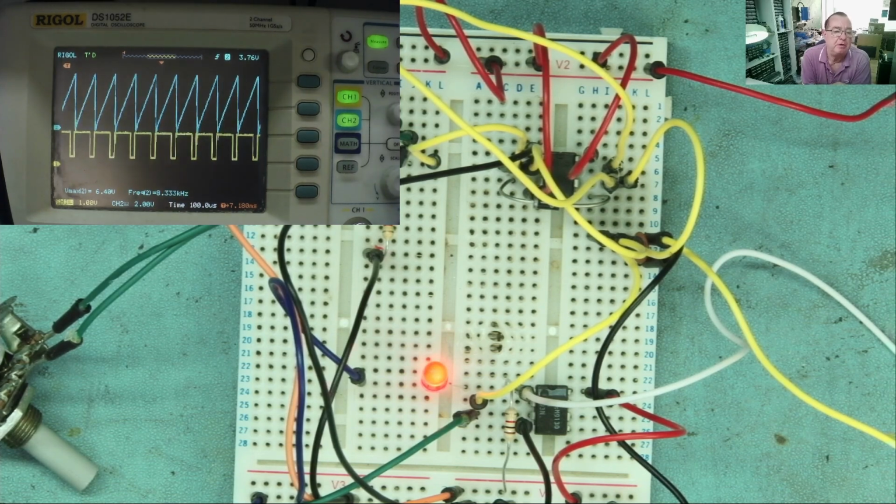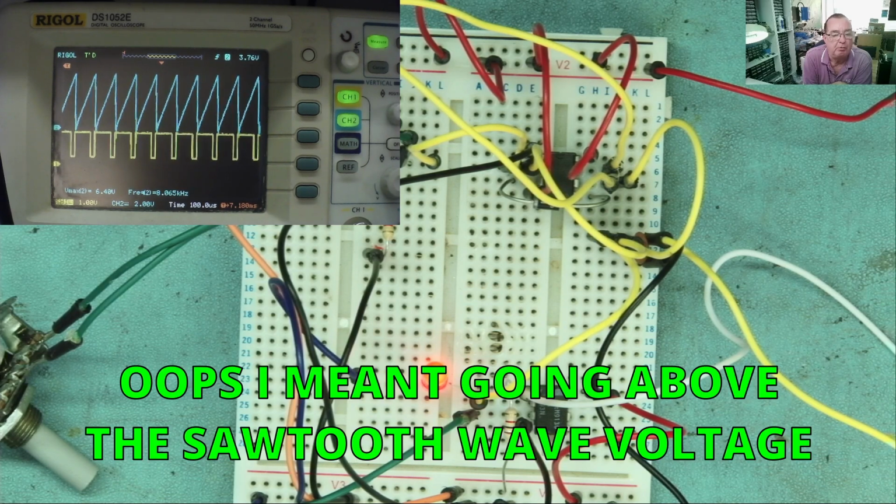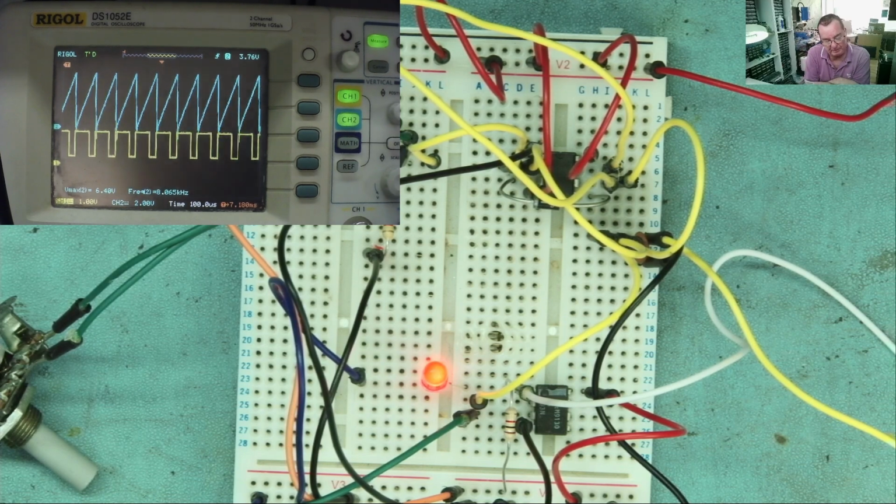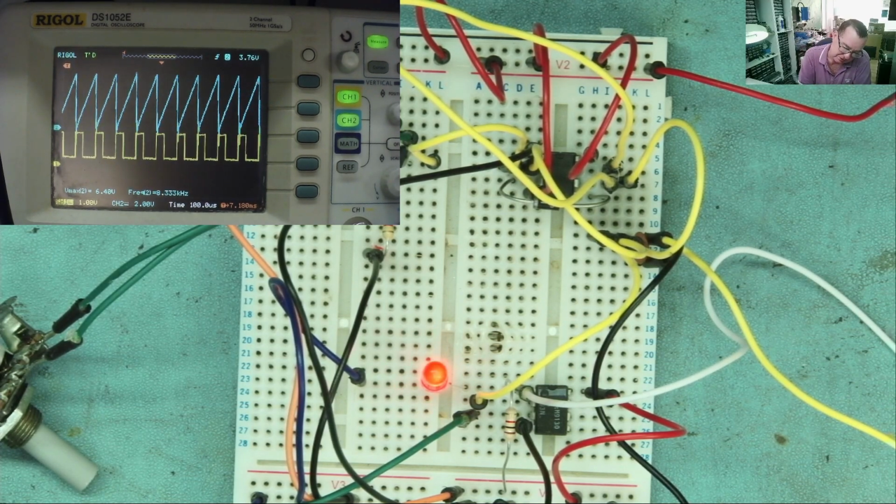Okay, so now we're running at 0.1 Hz, so you can clearly see the pulse width modulation at that speed. I don't have quite the amplitude set, so it looks like the incoming sine wave is actually going below the voltage of the sawtooth. That's why it goes below 0 duty cycle, just there. Okay, but with a little bit of tweaking, we can make sure that it's stayed within range and it's not going quite to 100%. And once again, our LED is flashing on and off slowly.